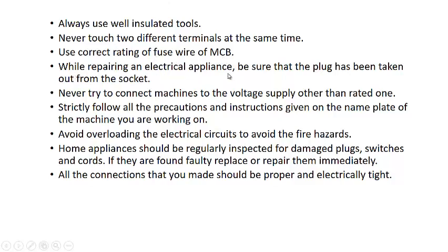While repairing an electrical appliance, be sure that the plug has been taken out from the socket. You should not only switch off the socket. You should take the plug out, to be on the safer side, so that if the switch has some problem while switching it off, you will not get any electric shock.